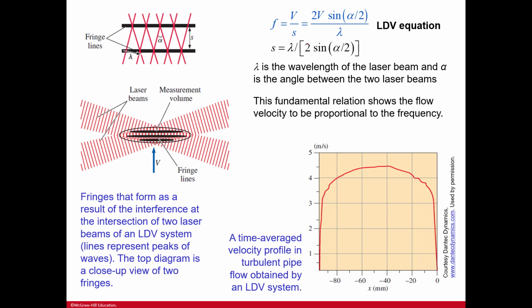Here are LDV equations, just things that work with that, and schematics for a time average velocity profile in a turbulent pipe flow.